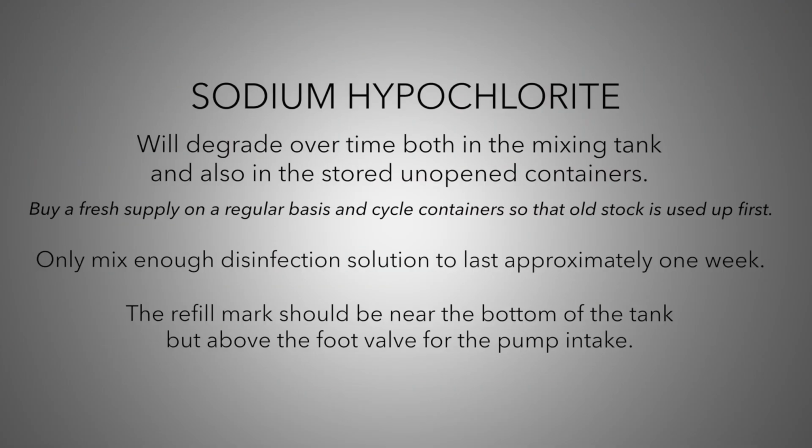At this point, we should discuss some important properties of sodium hypochlorite which can affect its performance as a disinfectant. Sodium hypochlorite will degrade over time, both in the mixing tank and also in the stored unopened containers. It is good practice to buy a fresh supply on a regular basis and cycle containers so that the old stock is used up first. It is also good practice to only mix enough disinfection solution to last approximately 1 week. The refill mark should be near the bottom of the tank but above the foot valve for the pump intake.